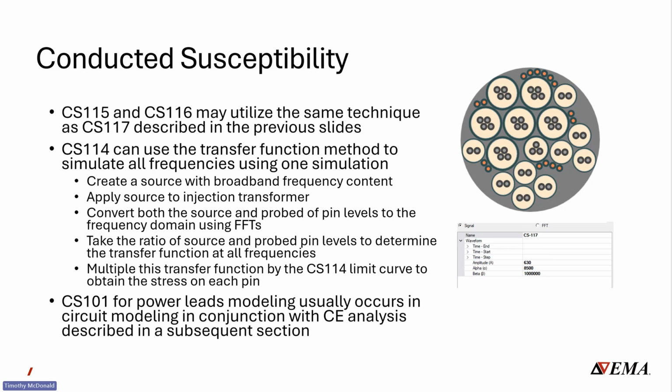This way you can determine what they are, add protection devices, commonly a diode placed on the line that will clamp at a voltage above the operational voltage of that line. You need to understand the worst case transient so you can properly size the diode. You don't want to oversize it because it adds physical weight to your system. So every designer needs to be able to do that.